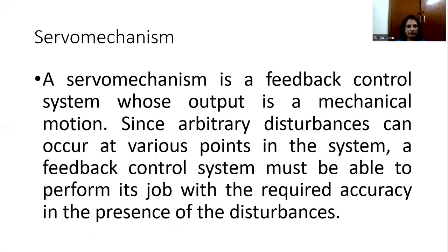Then another class of systems that is very important in the case of control are the servo mechanisms. A servo mechanism is a feedback control system whose output is a mechanical motion. If we talk about servo mechanisms, then we are simply talking about systems where the variables of concern are position and its derivatives.